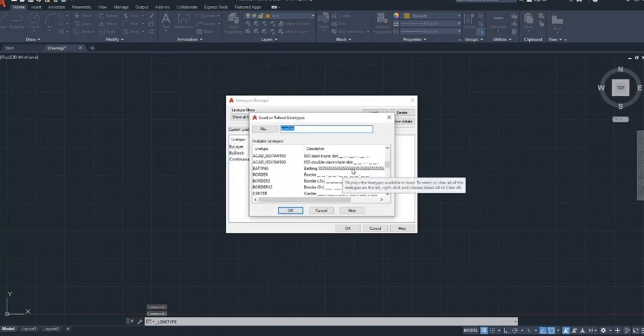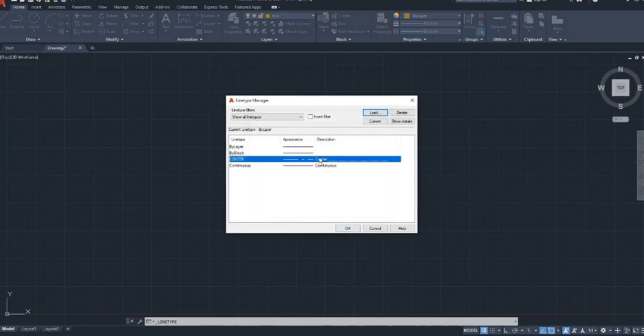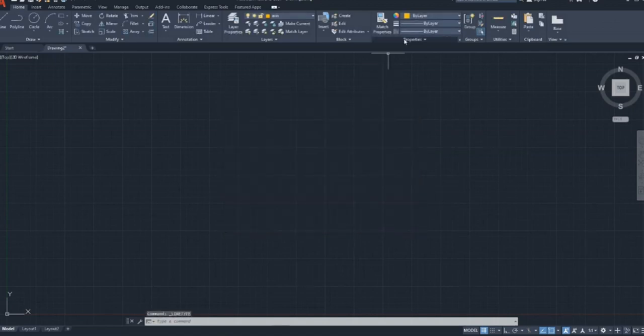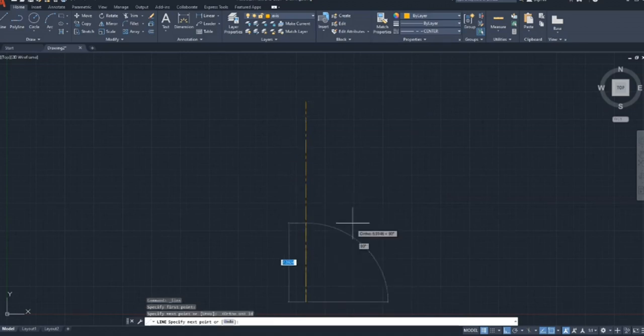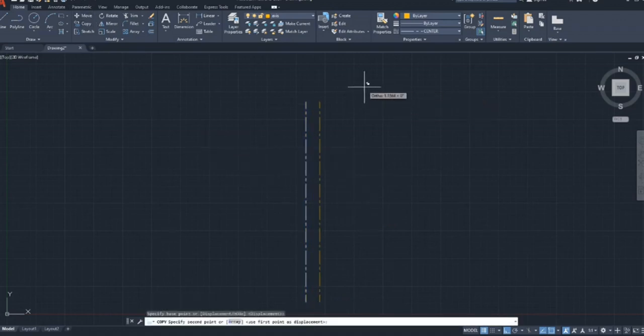For this, the axis layer needs to be selected. As I mentioned before, the line type was not selected earlier, so we will have to give an appropriate line type. In most cases, a center line is recommended to draw axes. Well, axes are some reference lines, so that specific layer could be turned off later on if it is not required.